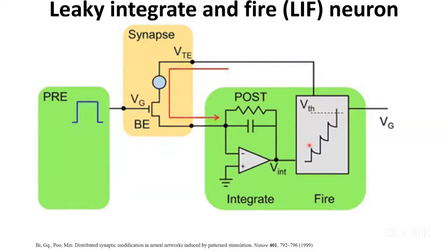So far I hope that I have covered the background of neuromorphic computing. And now what is important to understand is how ferroelectric FETs come into the picture, and how we can improve the implementation of the neuron from this conventional architecture where we use a capacitor and an integrator, and then how we can improve the synapse. Synapse is a memory that is required to store data. So these two things, how we can do them using ferroelectric FETs, we'll go one by one.